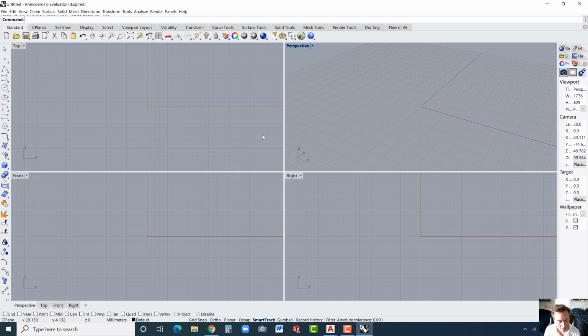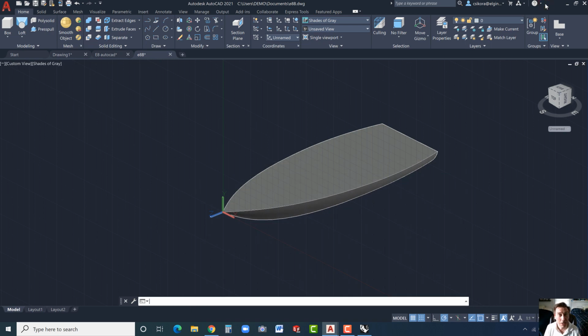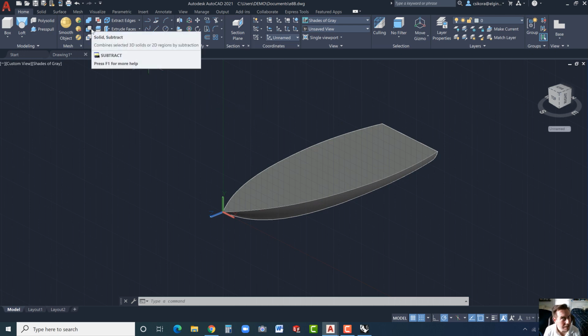And this software, actually, there is something called Flatten. I believe it's Flatten. Yeah, Flatten Surface. And you'd be able to select it. It doesn't always work the way you'd expect, especially on very complex surfaces. We could try it on here, though. And this is what you would want to do, those of you. And you could do this with any CAD system.